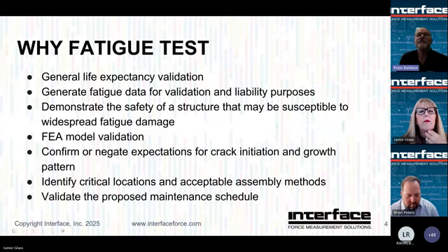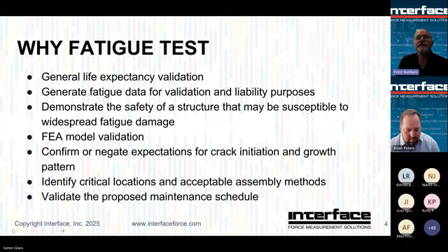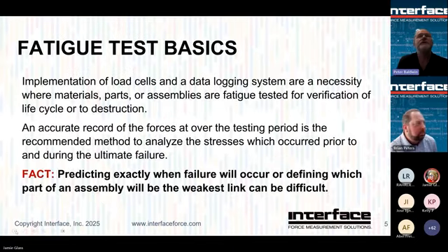And we want to be able to demonstrate the safety of a particular structure that may be susceptible to widespread fatigue damage, FEA model validation, confirm or negate any expectations for crack initiation and growth pattern, identify critical locations and acceptable assembly methods, and then validate the proposed maintenance schedule. All of that is incorporated in what we're going to cover today.